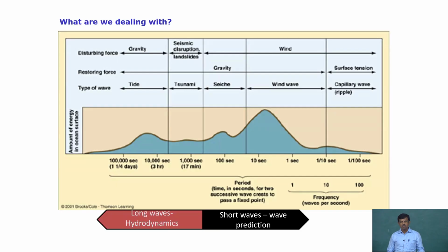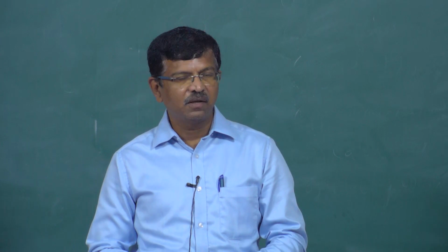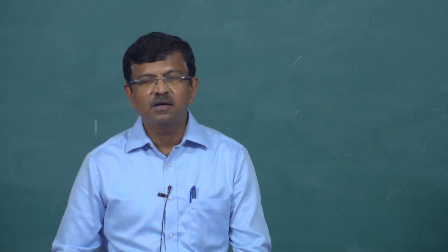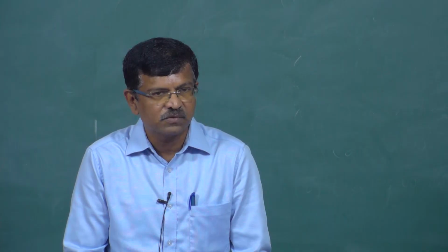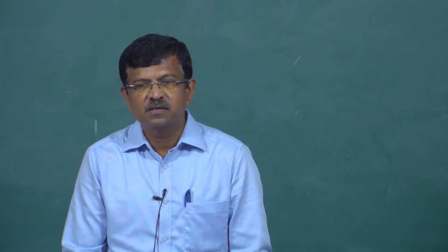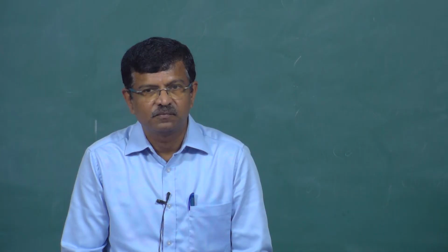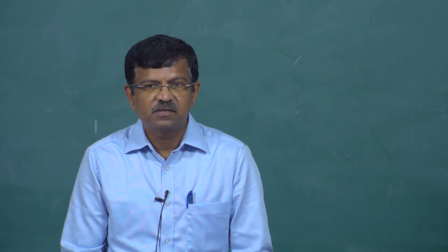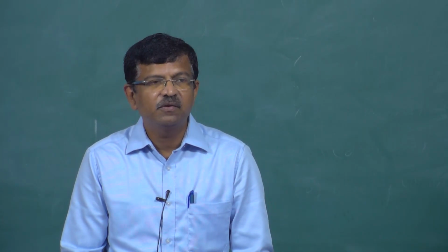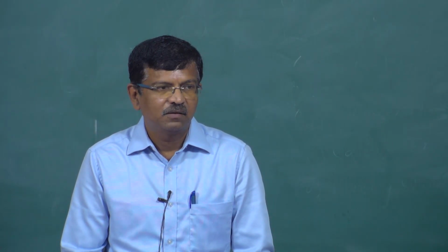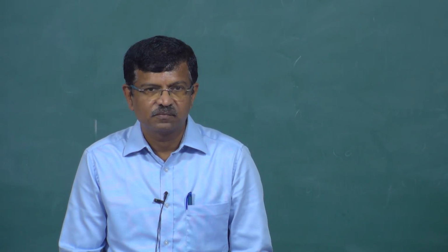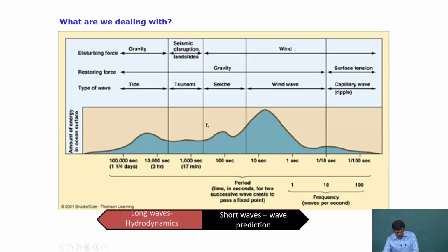Another important component, in narrow regions like a Gulf or like Sundarban in India, is that current also can be a dominant thing in addition to rivers etc. Current is again generated by the wind induced waves, but that current intensity is much less in the open ocean. However, when there is a tide induced current, wave induced current will have an aggravated effect on a particular coast. Tide has a 12 hour and 24 hour period in this particular region.